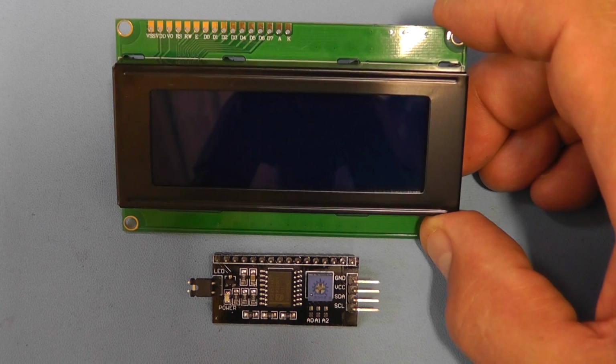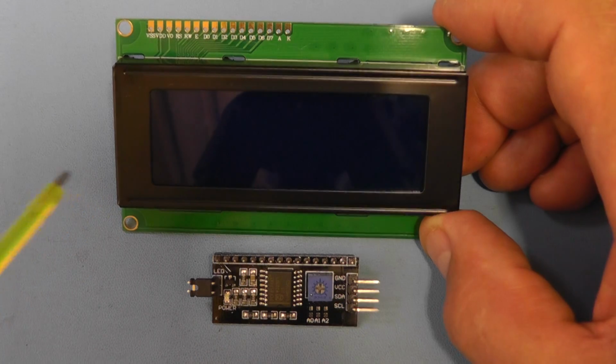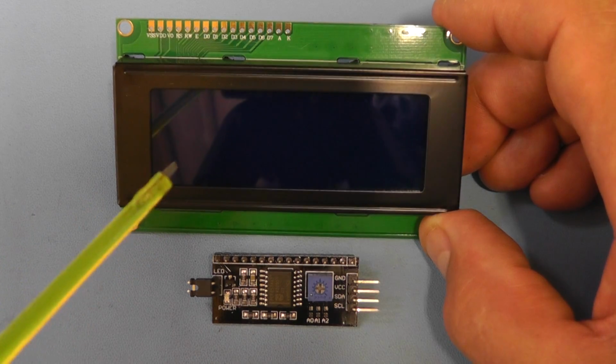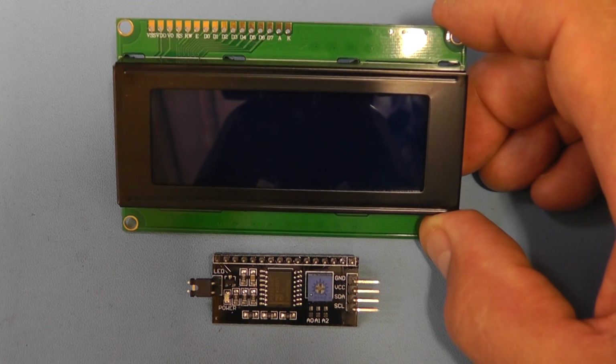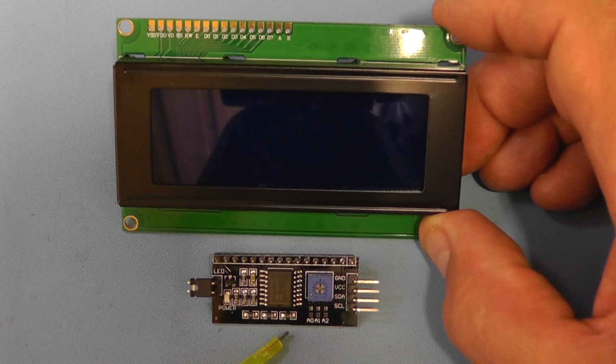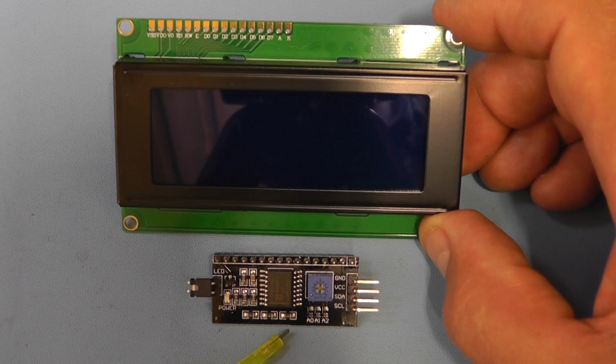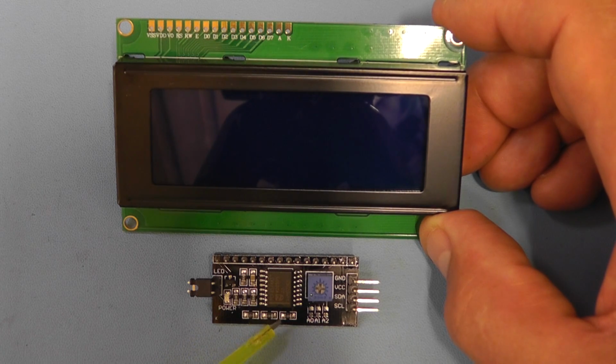Here we have the display module that I'm using on the project. This is the 20x4 display, and then just below it there you'll see we've got the little adapter module, the I2C bus adapter module, and that's using the PCF 8574 input-output expander IC there, you see, which is a Philips IC. And you've also got a little trim pot there, which we can alter the display brightness as well.